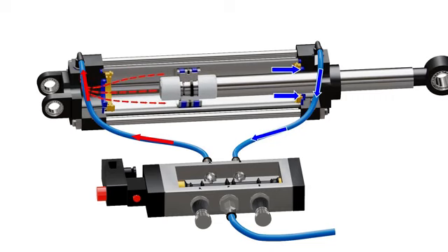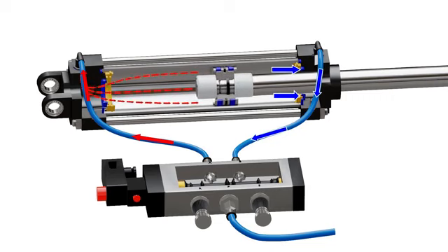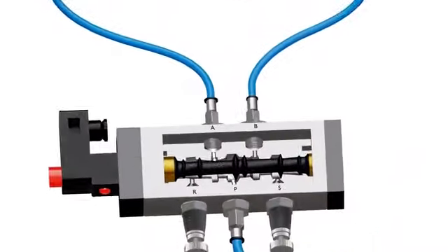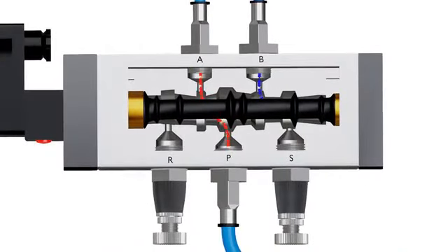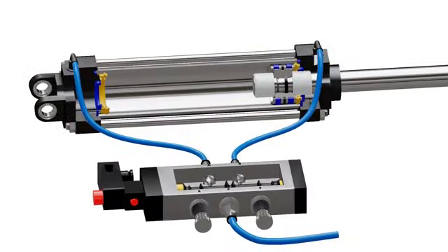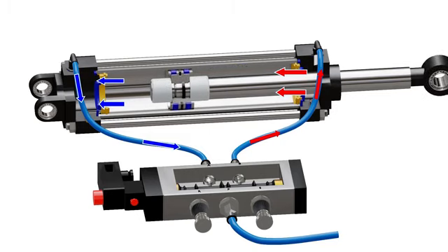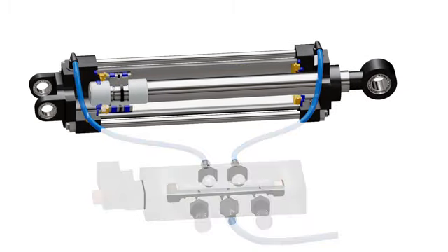This also pushes gas from the head end. This exhaust gas travels through the other hose and reaches the valve. The valve directs this gas towards port S and allows it to escape through a pneumatic muffler. The gas muffler helps to reduce any noise produced during exhaust. The process we just observed is the extension stroke of the actuator. During a retraction stroke, the valve directs compressed air to the head end of the cylinder. This causes the piston to return and air in the other chamber escapes from the exhaust port R.